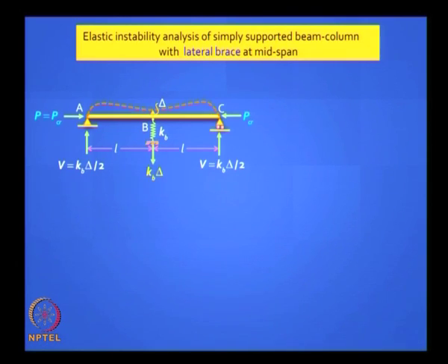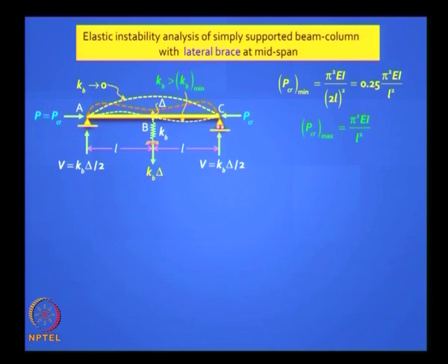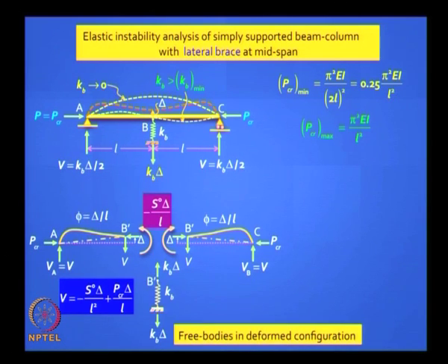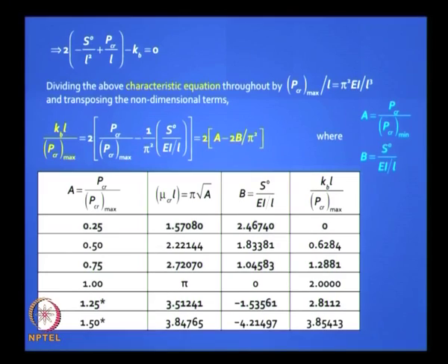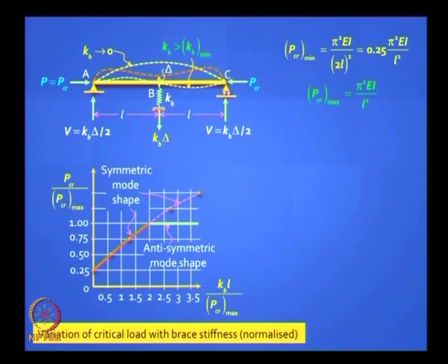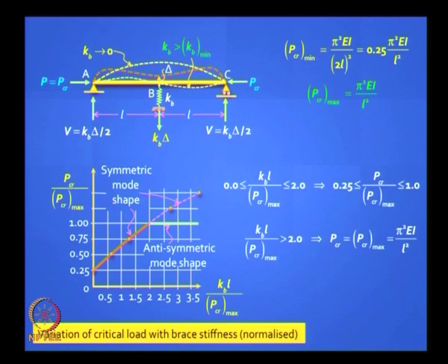Well, I can prove it from first principles by solving this equation. I can write my equilibrium equations, I write my stiffness values. You can do an equilibrium study of this and solve the equilibrium equation. Here you have moments coming into the picture, which were not there when you had the hinge, and the moments are related to your stiffness measures. So plug in those values and solve the equation. It takes a little while, it's explained in the book, and you will get an interesting result. You can find the critical value, and it turns out to be exactly the same solution.